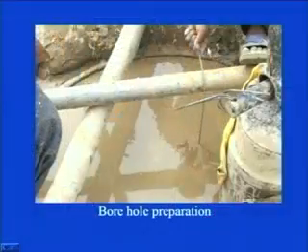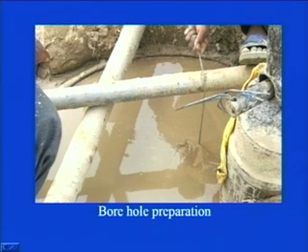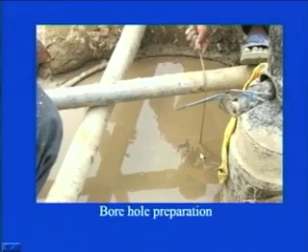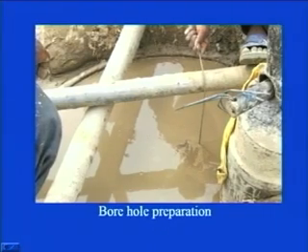So you see here a worker, he has put some weight on this cable. With this cable he is trying to measure at what particular depth the soil has been taken out. Let us say you have to go for 30 meters. So there should be some measure to ascertain whether you have reached that particular 30 meter length or not. This is a kind of check that they provide at the site.